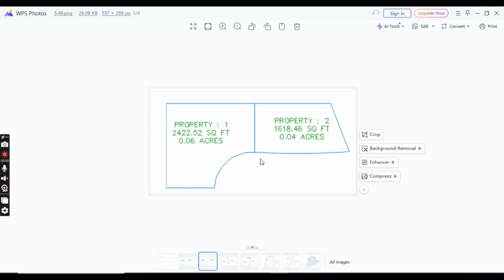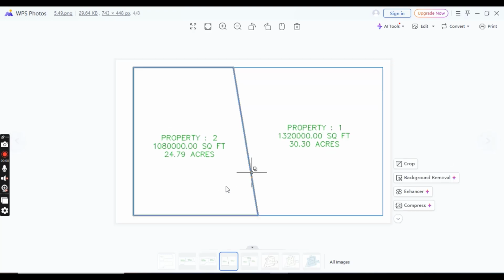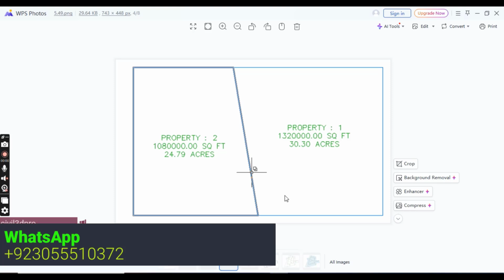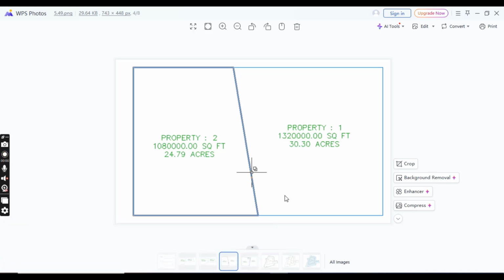A mistake that many people new to Civil 3D make is to create parcels from a closed polyline, which results in a duplicate segment between parcels like this figure. These two parcels may appear identical to the two shown in the previous example because they were both created from a closed polyline rectangle. However, the segment between them is actually two segments.